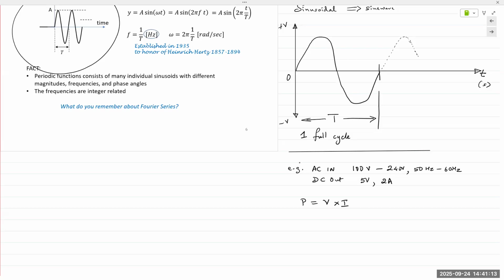Then came along fast chargers. Instead of 2 amps, you now supply 3 amps, 4 amps, 5 amps. So now you have 50-watt chargers. So you can supply 5 volts, 10 amps. Then came along USB-C, USB-C power delivery. USB-C PD not only allows an increase in current, it also allows an increase in voltage. So depending on the device, that power supply can mix and match, or cross supply increased voltage and increased current.